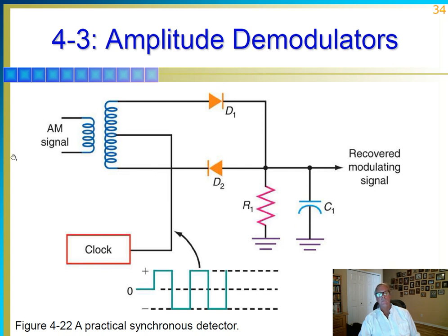So what happens is we pull in the AM signal, we filter it just to get the carrier, feed it into this clock circuit down here. This clock circuit is essentially a phase lock loop. It locks to that and creates this synchronous detector signal. That's something that's left out of this block diagram. Sort of this behind the scenes thing that's going on here. We'll talk about that a little bit more when we do our phase lock loop.